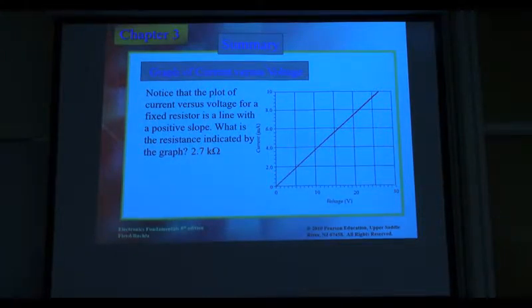When you calculate the resistance, for this example you can easily calculate. The resistance equals the voltage divided by the current. So the voltage, again, we pick this point, and this point may be at 25, 26, 27. So this one equals 27. So 27 divided by 10 equals 2.7. Why is it K? Because this is a V, this one is a milli, so negative 3 on the bottom, so it will be positive 10 to the positive 3 on the top, so that's why it's K. Make sense? Okay.